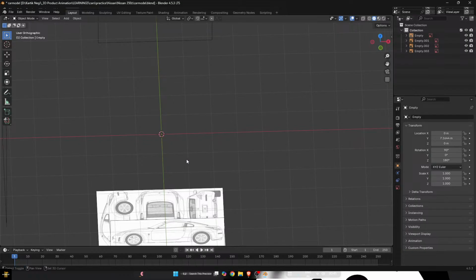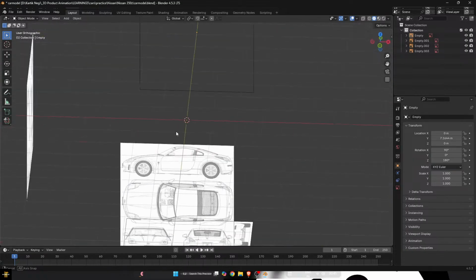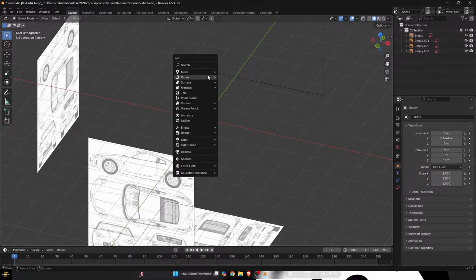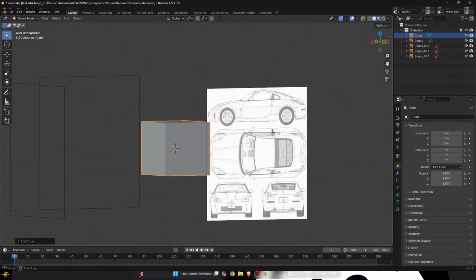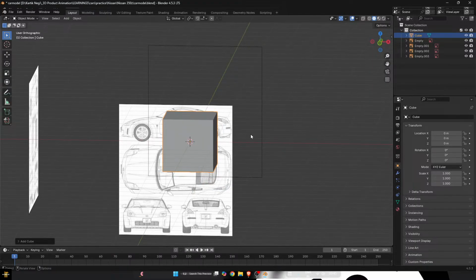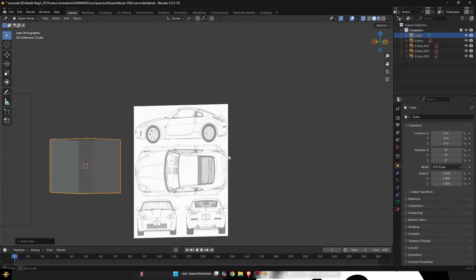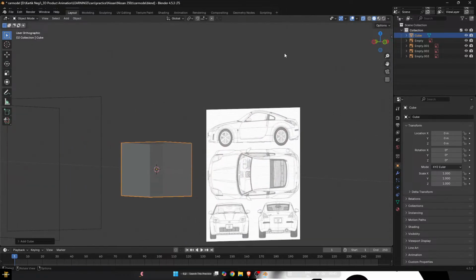So what I'm going to do right now is by clicking on Shift A, I'm going to introduce a mesh that is cube. So this cube is over here, and I'm just going to press Alt Z to make its X-ray view. We can also do it by going over here. So you can see toggle X-ray can also be accessed by clicking on the shortcut Alt Z. So when you click on it, you can get it. Otherwise, you can click on Alt Z.